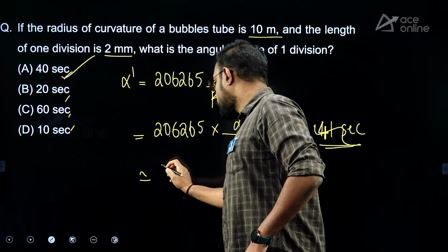Okay, now? Yes. Okay, look at this. In chain surveying, which is the instrument used to set out right angles? Ranging rods are used to find intermediate points. Plumb bob is used for centering and checking verticality. Alidade is not used in chain surveying. It is used in plane table surveying.